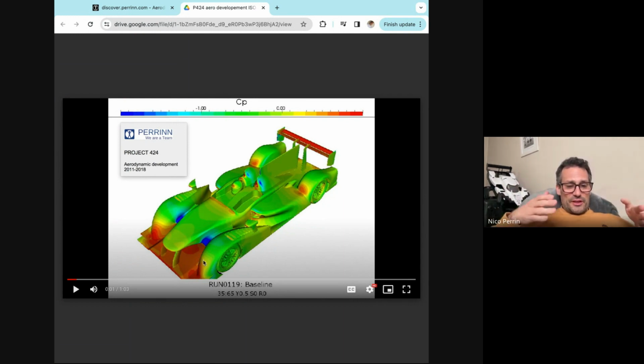The wheel arch was an idealized surface that was sealing the suspension legs going through. So it was creating a very smooth channel for the air to go before it exits at the back. The idea was I'm trying to isolate the air from the inside of the wheel arch, so the air couldn't go inside the wheel arch from under the nose, if you see what I mean.